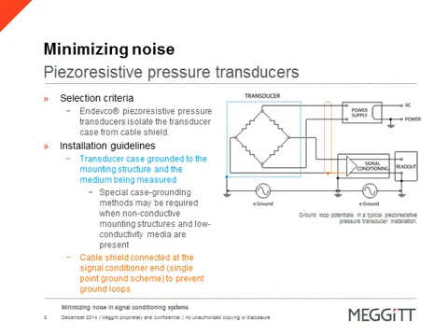Piezoresistive transducers. All of the Endevco pressure transducers have an isolated connection from the signal ground to the actual case of the pressure transducer. So that's important and is needed to know to properly connect this system.